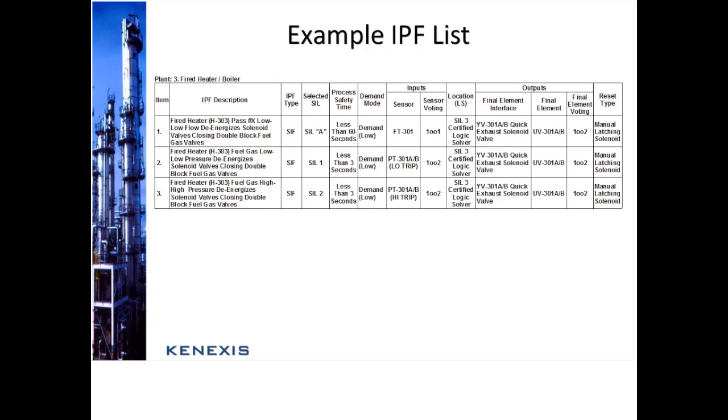The second SIF is a 1 out of 2, and the third SIF again is a 1 out of 2. Location logic solver, in this particular scenario, was defined as a SIL 3 certified logic solver. Some third party, TUV, Exida, or somebody else has defined the certificate for this piece of equipment, and it's a certified logic solver.